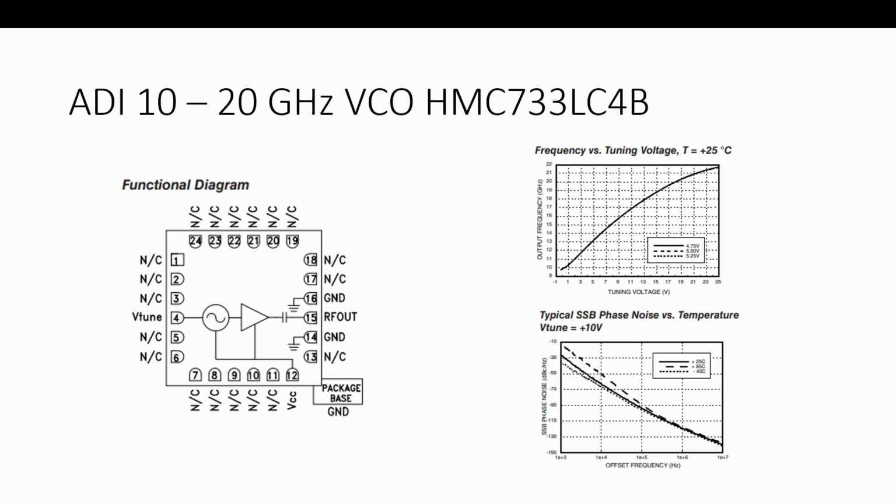We're looking for, hey, what's its tuning sensitivity? So as we tune it, what's its output frequency doing, right? And then we want to look at what is its phase noise, because we're doing this whole thing, locking it to something to clean up its phase noise rather than run it open loop. So we have a phase noise, and phase noise in simple terms is, if you have a pure output frequency and the phase isn't changing, there's no phase error, then it's the cleanest thing in the world, there's no phase noise. If the phase versus time is modulating, right?